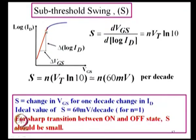When you take this slope, ln I_D, for example, delta ln I_D may be ln 100 divided by ln 10. So, ln 10, that is log 10, will be equal to 1. That is why when it is 1, you get 60 millivolts per decade. If you take this as 1 decade, how much is this? That is the subthreshold swing. So, the best value that you can get.